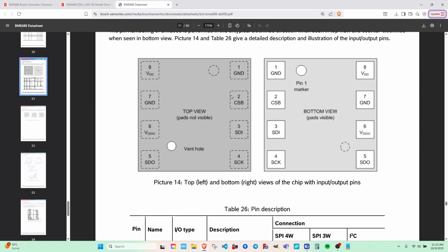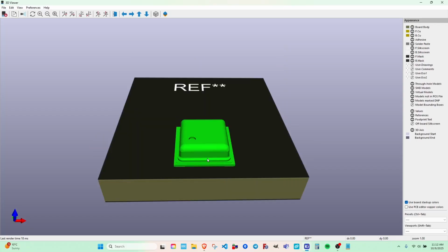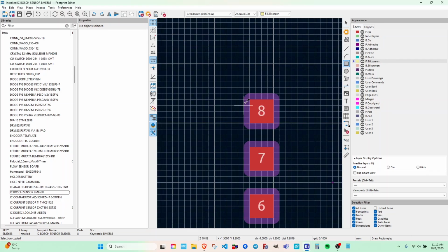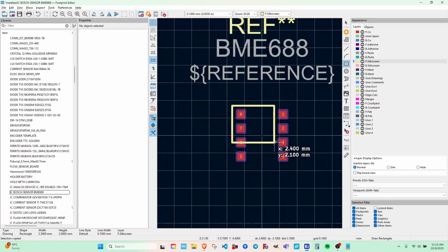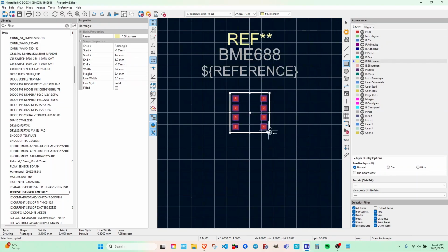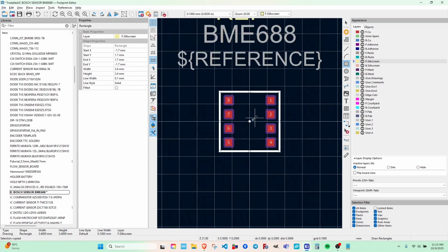And if we hit Alt-3, how close is it to the pads? Fairly close. So we'll draw a little bit outside the pads and go from there. So we'll click our draw rectangle and we'll start maybe 1, 2 diagonal, okay? And come down here, 1, 2. So it's nice and symmetrical. And you can see it's symmetrical because the center point is right on the center, our 0, 0 XY value there.